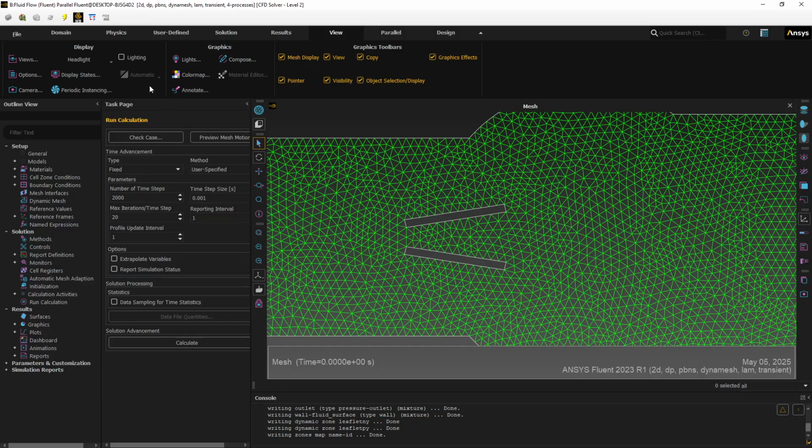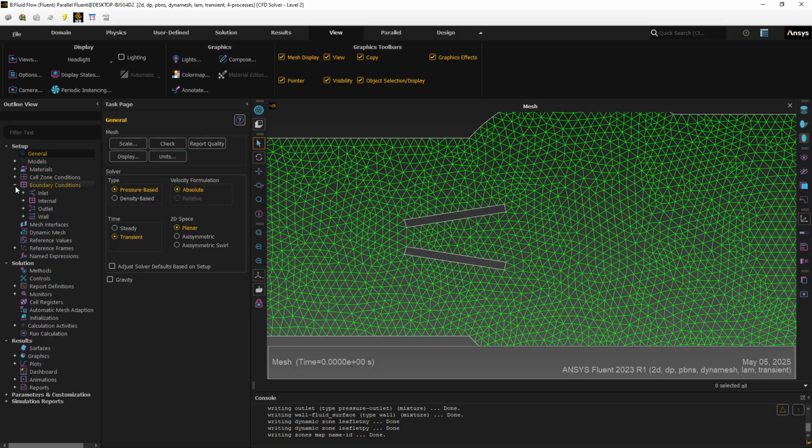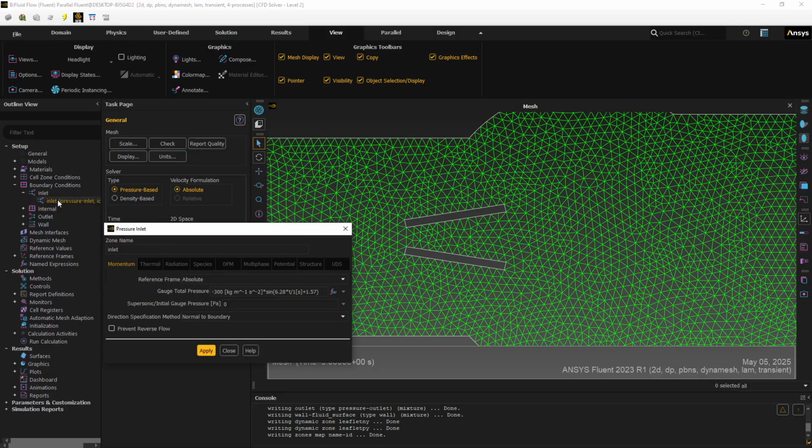The nice thing about this method is almost everything is maintained. It remembers the transient and it remembers all the conditions. So if I wanted to change something, here is where I can do that. I could change the pressure from 300 to 200 and get a new result.